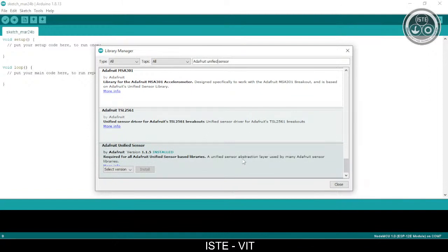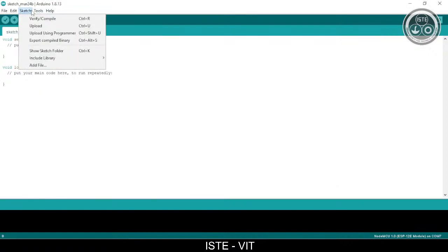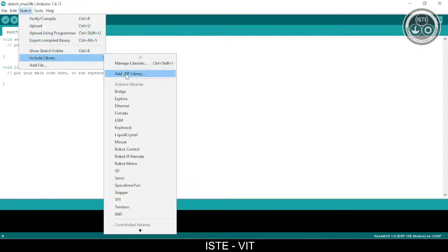This library is used to run the Arduino programs inside the NodeMCU, because Arduino is an AVR platform, and DHT11 is specially designed for Arduino AVR platforms. So now we require this DHT to use in NodeMCU, right? So for that we will be using this Adafruit Unified Sensor library. As its name says, it unifies all the sensors, and it makes them work in the NodeMCU as well. Install this too. If you're downloading directly from GitHub, just click Sketch, include library, add .zip library. Just browse to where your zip file is downloaded. Double click, and the library will be directly added.